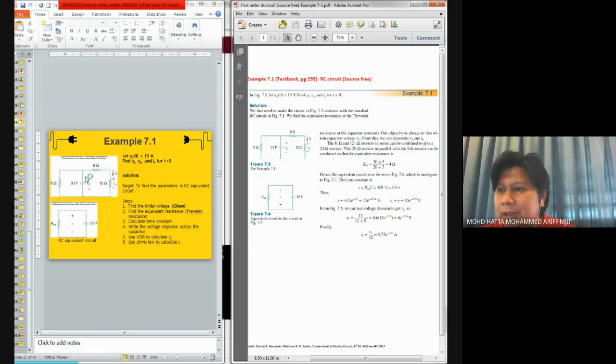If you look at the circuit itself, it's a parallel circuit, which means that if you sum the voltage drops at the 8 ohm resistor and the 12 ohm resistor, it equals VC. The same goes for this 5 ohm resistor. For example, if I ask what the current over here is, you can use the information of VC and divide it by this 5 ohm resistor to get the value of current flowing through this branch.